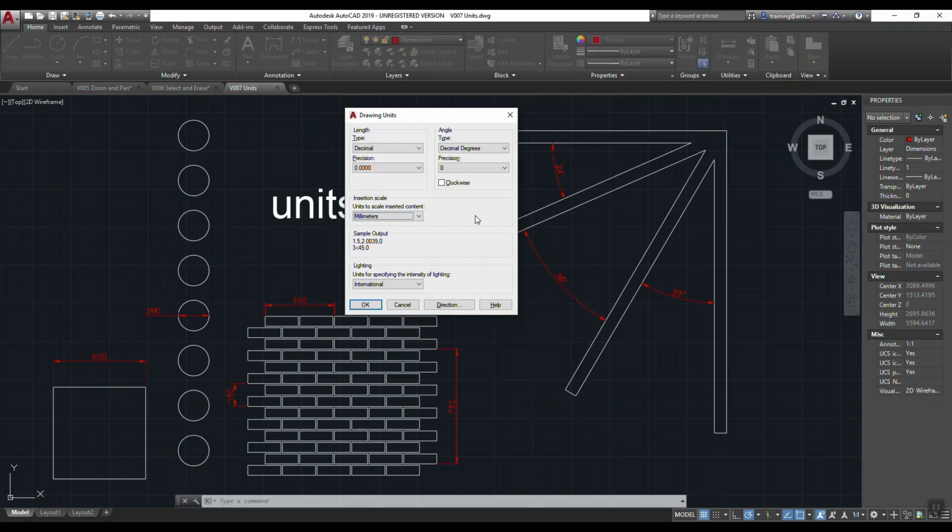So you choose it and you stick to it. And my advice is that once you've chosen millimeters, for instance, for your drawings, then stick with millimeters for all of your drawings, so that you can easily use some of the drawings that you will make as symbols, and therefore the size of those drawings that you're going to be inserting into AutoCAD will still be a predictable size.